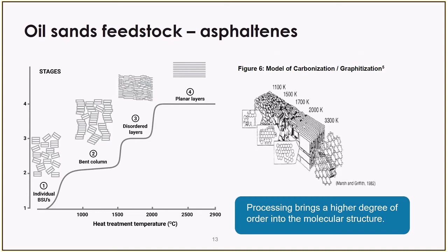So through this process here, you can see the high temperatures, alignment and orientation, removal of impurities, and we want to get to what Axel mentioned previously, which gives carbon fibers their strength, which is the layered hexagonal structure. Off on the right-hand side is a visual of what happens there. So we'd have our raw asphaltene moving through these processes of getting them structured, removing impurities through different processes to give us at the bottom right-hand side that hexagonal structure, which really gives us the strength in carbon fiber.